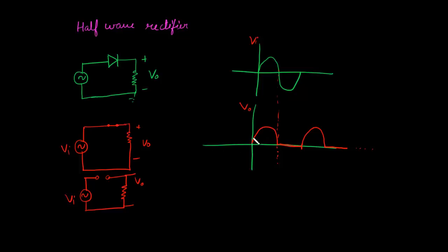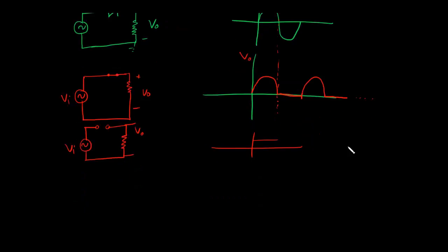If the average of this cycle is calculated, then we can get almost a DC signal after using proper rectification. We see that this diode can be used as a half wave rectifier. Next we can see the application of a diode as a logic gate.